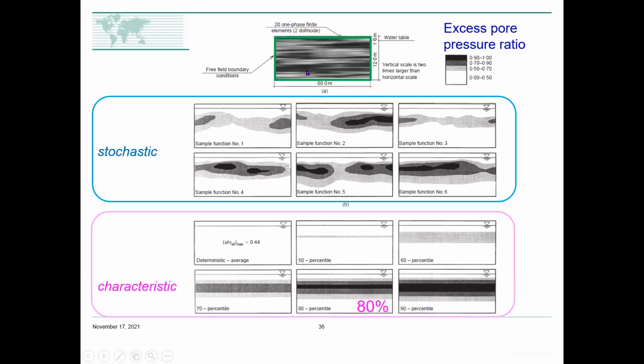Now, we don't know the details here. We only know the average tip resistance. We know the standard deviation with tip resistance, and we know the trend with depth, and we can come up with the spacing parameter saying it's perhaps 20 meters between or the continuity of a particular dense layer, maybe 20 meters or thereabouts, and we can randomize that as well. And so we have a statistical thing, and we numerically in the computer roll the dice.